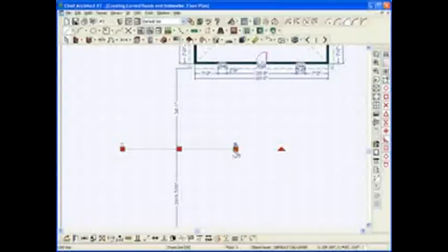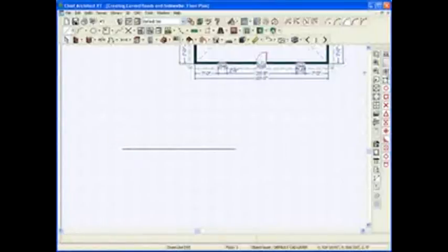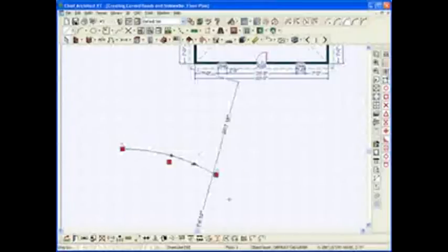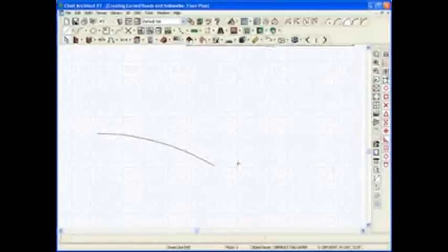I'm going to grab this end handle right here, and I'm just going to hold my Alt key down. I'm going to bend that line into an arc. First of all, you'll notice it snaps now. It's snapping at specified degrees, 15 degrees. I could go up here and turn that unrestricted angles off, and now when I grab that line, hold my Alt key down, I can bend it pretty much unrestricted any way I want to. So I could turn that line into an arc.